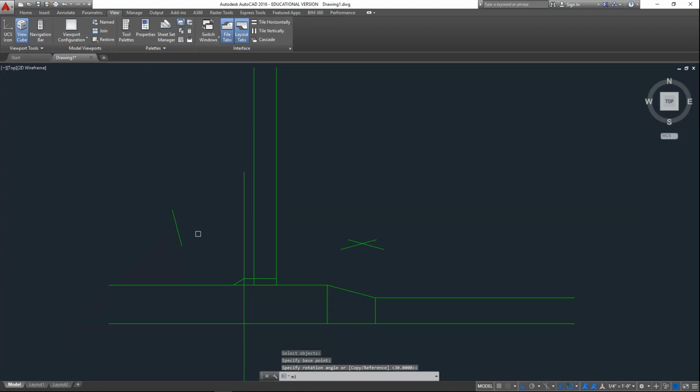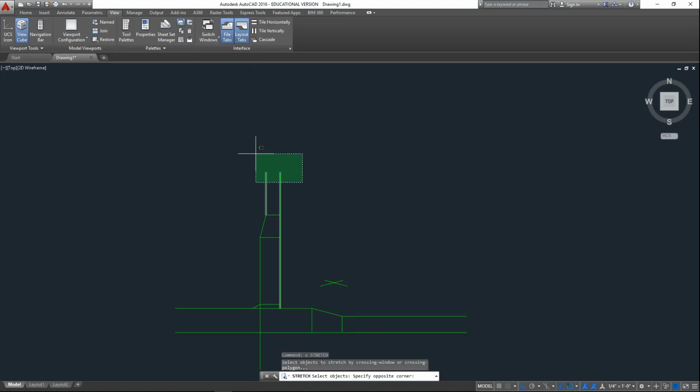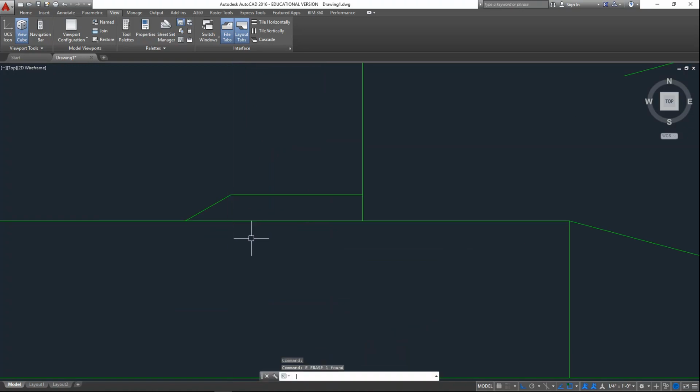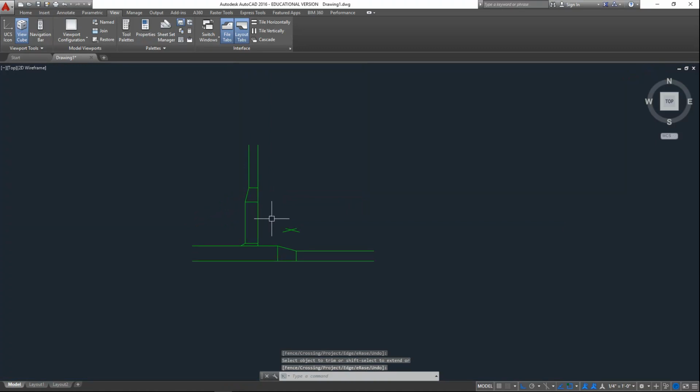And it's gone the wrong direction, so I'm going to mirror it. And I'll pick it up and move it from the end point to there. Do fillet, do a line from the end point to the perpendicular, line from end point to perpendicular. And then I'll just stretch these lines out a little bit. I'm going to trim this off again. At this point I can put some lines on the end, the ductwork, close those off.